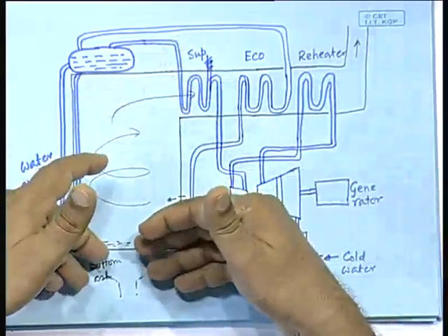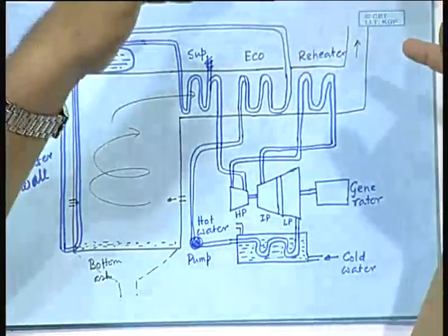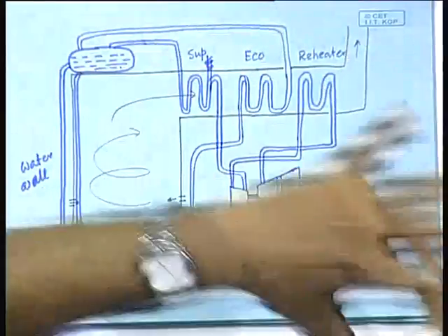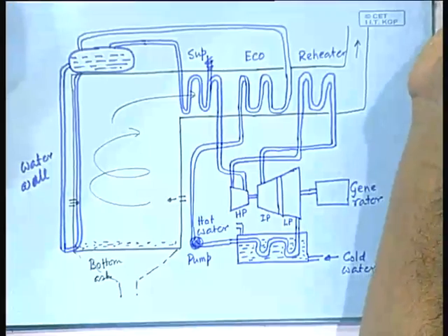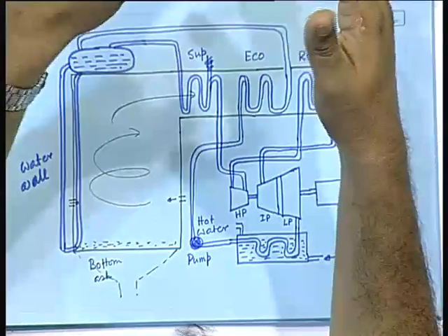The problem is that initially when a power plant is installed, nobody really thinks about this problem. They start thinking when it becomes really a problem, like 5 to 10 years later. Initially all this ash, both the bottom ash as well as the fly ash, is mixed with water, made into a paste-like thing, and carried by means of pipes into some ponds. These are called ash ponds, and naturally it keeps on accumulating in the ash ponds.